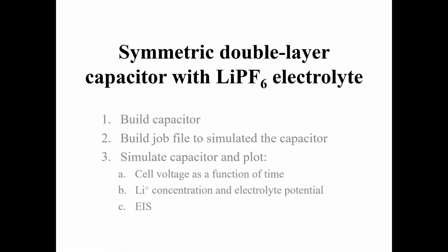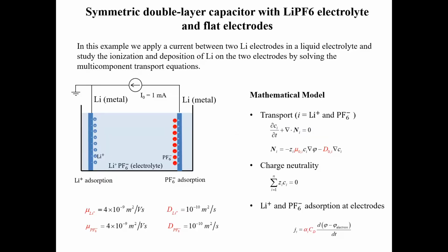be making an EDLC without a separator. And what we're going to be doing is simulating this capacitor by plotting the cell voltage as a function of time, the lithium concentration, and the electrolyte potential, as well as the EIS.